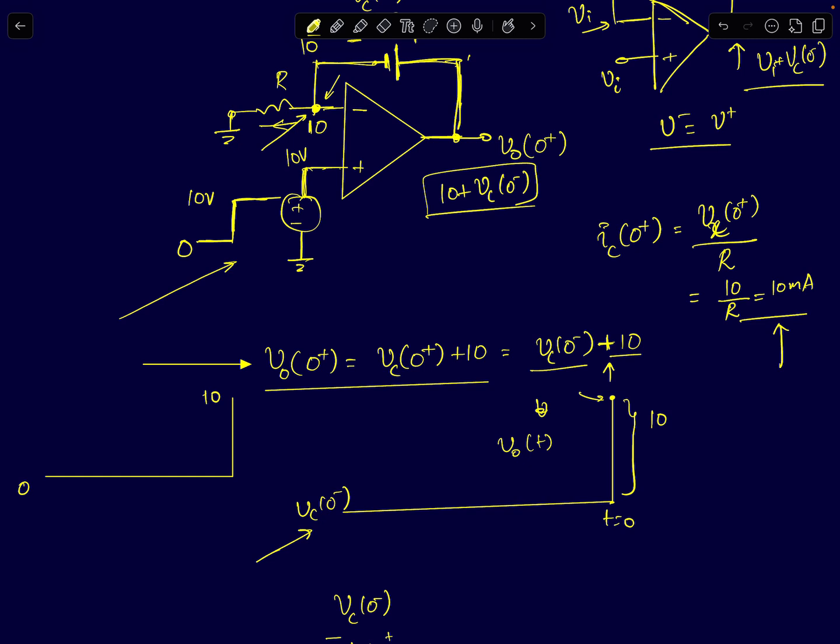If you have been noticing something as we are analyzing the circuits, there is a very interesting fact between differentiators and integrators. For integrators, there is a transient negative feedback. When there is a sudden change in the input, the integrator circuits tend to have a proper DC feedback, but there is no DC feedback in the steady state. The opposite holds true for differentiators. When there is a sudden step input or a transient event, there is no DC feedback. DC feedback happens only in the steady state. I'll solve more problems and this point will become clearer.